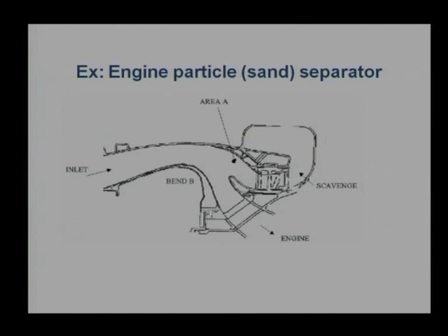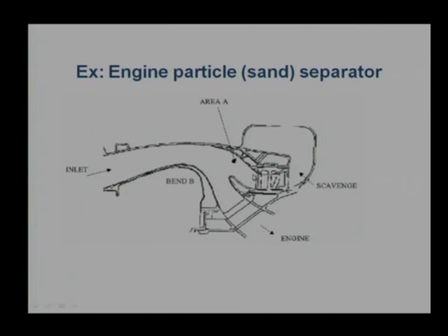To avoid that kind of pressure loss, generally they use this kind of design. They use particle inertia. Particles are coming with some velocity when getting sucked, and they will move simply in this zone. Air which can skip from that route, can change its route, because it has a very low inertia, can come this side. The problem is that to increase the volumetric efficiency, we require a really very large volume of air. In addition, this is not a foolproof method. Still, there is a possibility that a few particles will come.